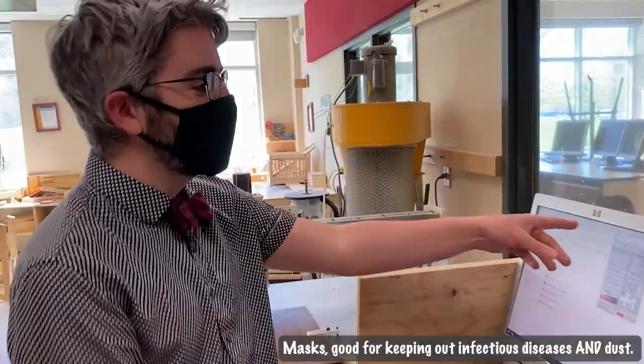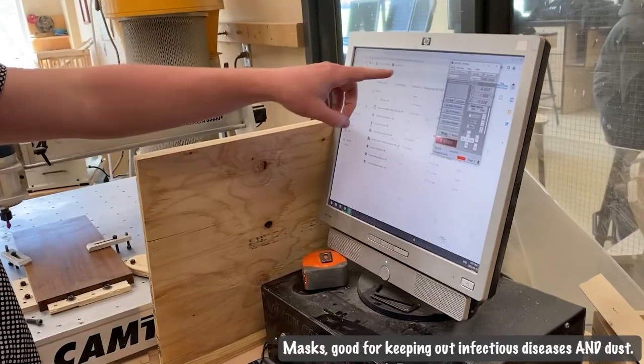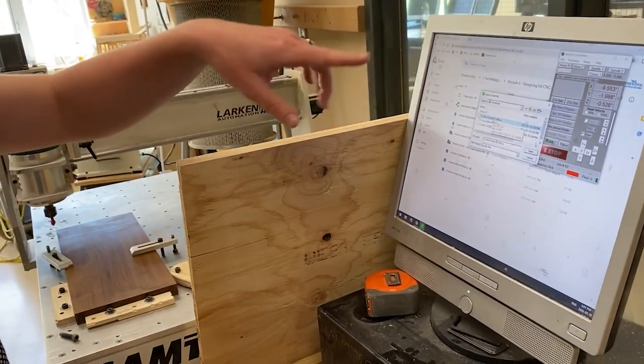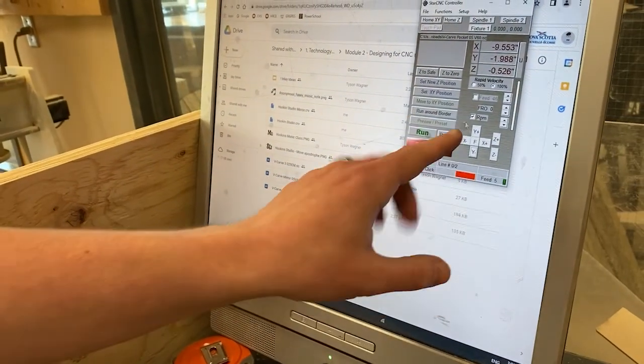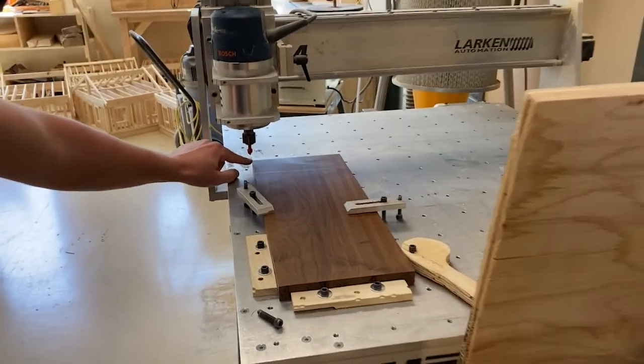All right, so I got the program open here that's going to communicate with our CNC router. I've opened up my first set of code. I'm going to do the pocket first, so we're going to open that one up. And now I just need to zero my machine. I'm going to use the controls here to get this router right down here at this point.